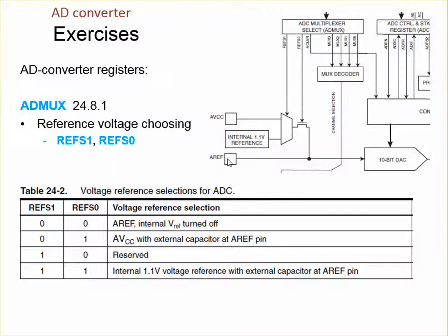The third option is to use our own individual analog reference voltage that we could connect here. So if we bring our own reference voltage to our converter, we should connect it here. And then we are of course not using these voltages. This FET will be in off state, so the reference voltage will go directly from our outside circuit to our converter.